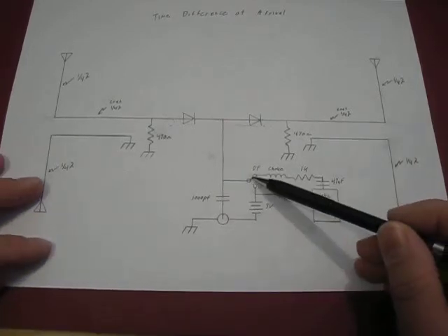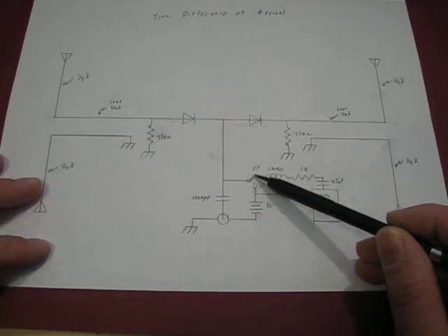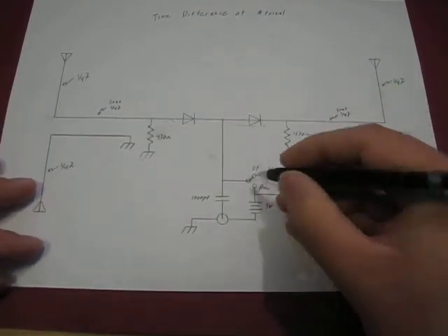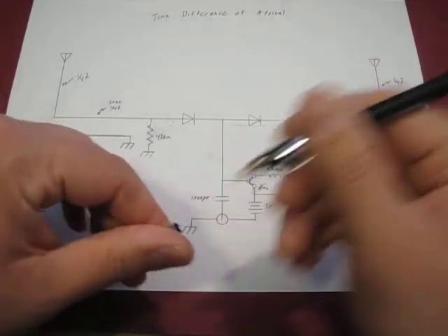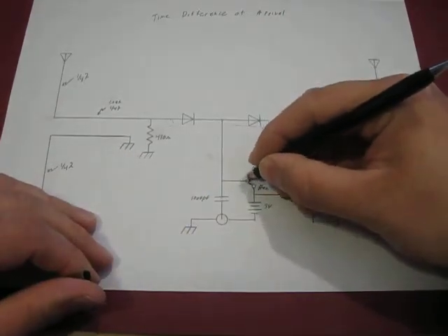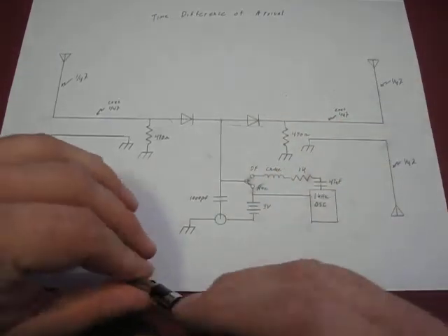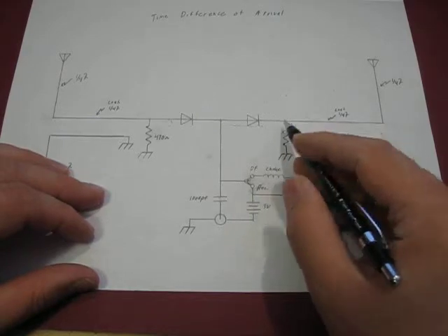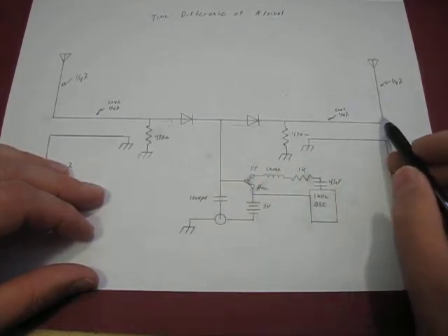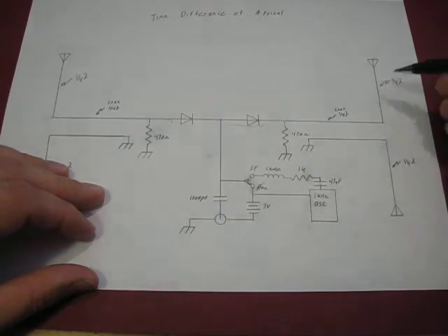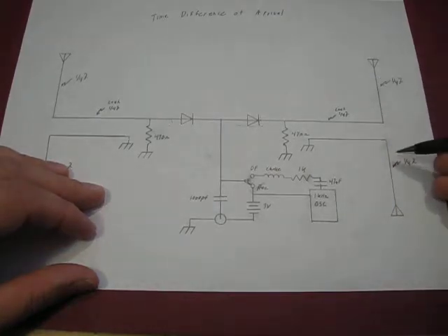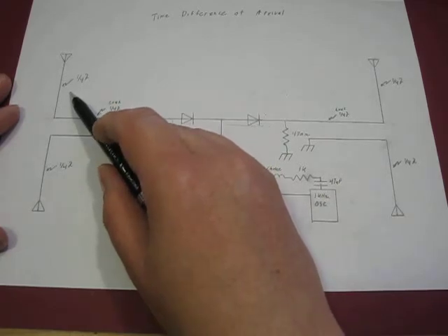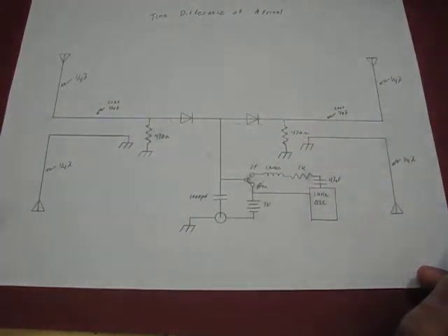And what they do is they have a little switch up here. It has DF mode, and then they have a switch, it's called receive mode. When you throw that switch to receive mode, it takes it off DF, takes that oscillator out, and look what happens. Now, this diode turns on, and basically what that does is it grounds out this element. So now this is considered ground, this is ground, and we have our receiving element here. So now it turns it into a little Yagi antenna.